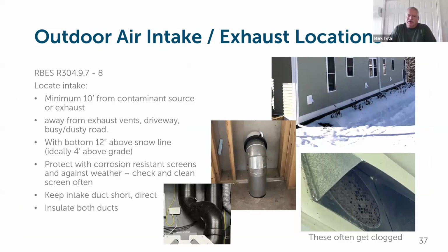All right. So, outdoor air intake and exhaust location. The top right picture is a great situation where you have the intakes and exhausts up high. That's very rare to see, because normally you're coming out at the sill at the bottom of the house, which would be in that white area, which is obviously too low to the ground for intake or exhaust. But Karen got this picture.